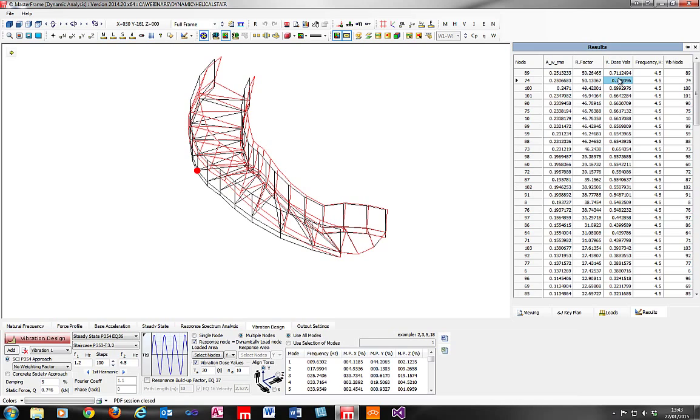So if your client is happy to accept the possibility of adverse comment due to someone using the stair, depending on its frequency of use, you may be able to convince someone that this vibration dose value is acceptable for the particular use of this structure. So that's something that might be interesting to some of you.